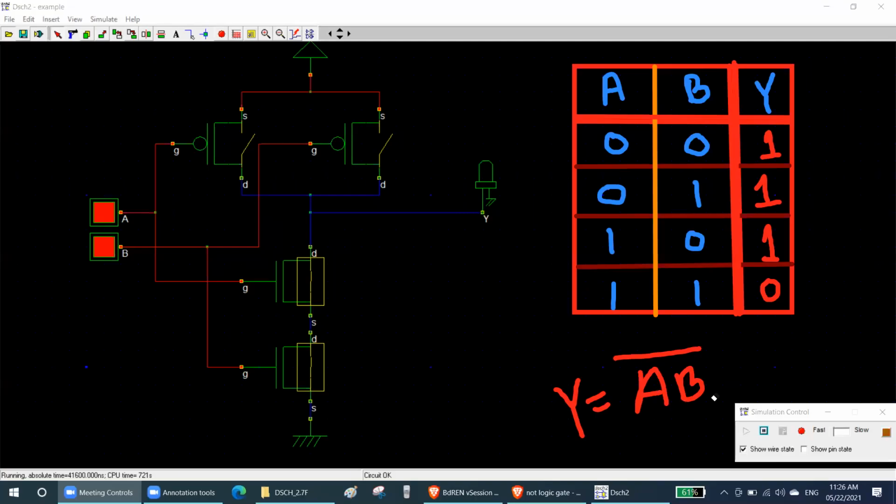Right? That does not have any power, just AB, right? Yes, sir. Okay. Do you know how to do that? Got any idea? Anyone? No. This is a very bad idea. Never. Your PMOS will stay at the top. Your NMOS will stay at the bottom forever. VDD will be at the top. Your ground will be at the bottom forever. You cannot change that.